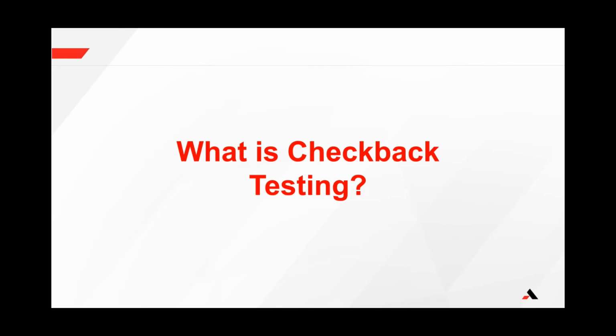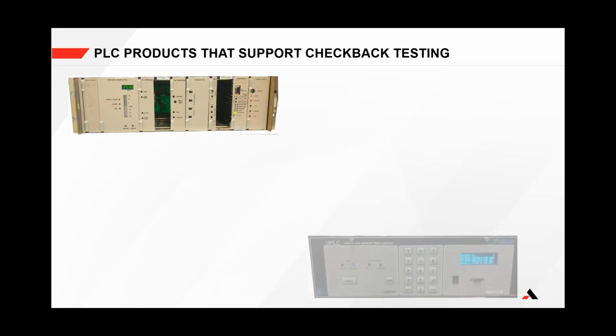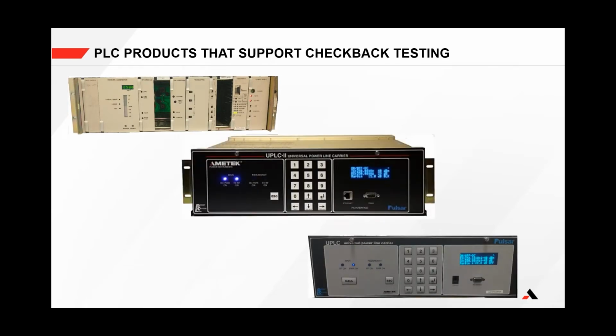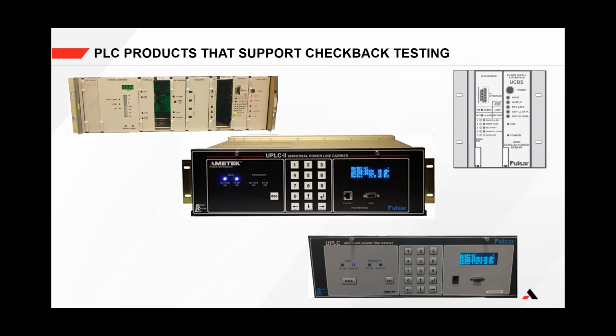What is checkback testing? Checkback testing is an optional feature supported in our older TC10B and UPLC, as well as our current UPLC-II carrier products. AMETEK also offers a universal checkback standalone product that can be connected to non-AMETEK carrier products to make them checkback testing compatible. The catalog number will reflect if your AMETEK power line carrier equipment has the checkback option.